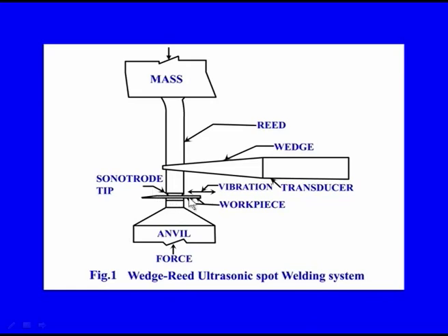The zone of interest means the workpieces to be joined are together, and there will be a light force applied onto them in addition to these ultrasonic vibrations. Under the vibrations, which are shearing in nature, and this light pressure, the materials in this zone where the sonotrode concentrates the ultrasonic vibrations will get locally heated and fused.